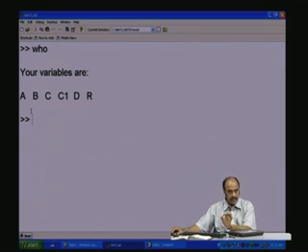Notice that MATLAB is case sensitive. So, it can recognize the difference between the uppercase and the lower case. Okay. Now, we do the first step in this analysis, which is the time domain. So, to do the time domain, let us see the step response. There are various responses that one can get, but for the purposes of understanding now, we will do the step response.